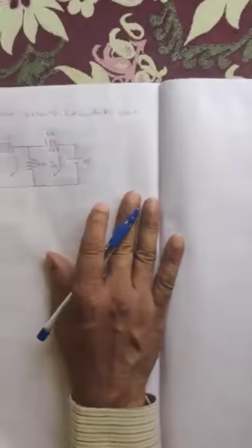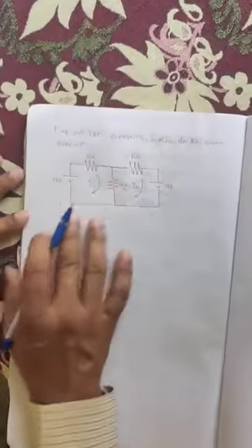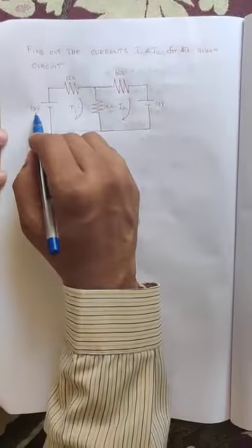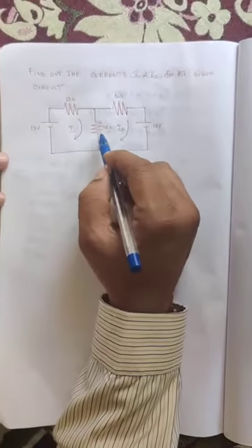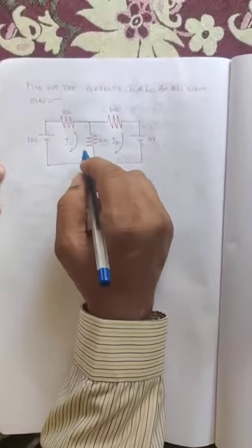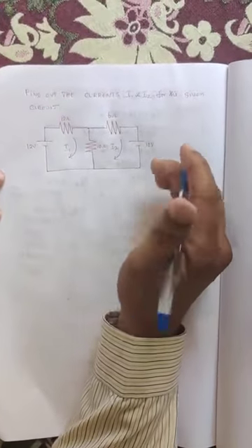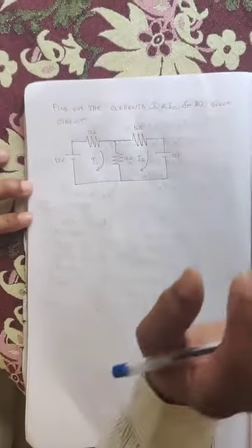Next, by using Kirchhoff's law, we are going to solve this given circuit. So here the circuit is given with two batteries, 12 volt and 10 volt. The resistors of 12 ohm, 6 ohm and 10 ohms are connected. And here Kirchhoff's law says the voltage drop equals the voltage rise, or the sum of the voltage drops and rises will be equal to 0.